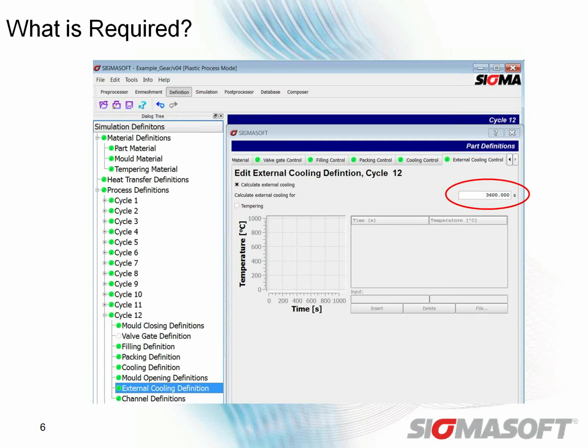But you typically see the most benefit in that first 30 minutes or 60 minutes, maybe 75 or 90 minutes, because most parts will cool within that time period. The longer time frames would be valuable if you're doing any type of tempering. As I mentioned, if you're going to apply some sort of heat or cooling to it after it's ejected, you can do that in the software as well. So we would check that tempering box, and then specify what temperature it's subjected to over what period of time, or some sort of profile.